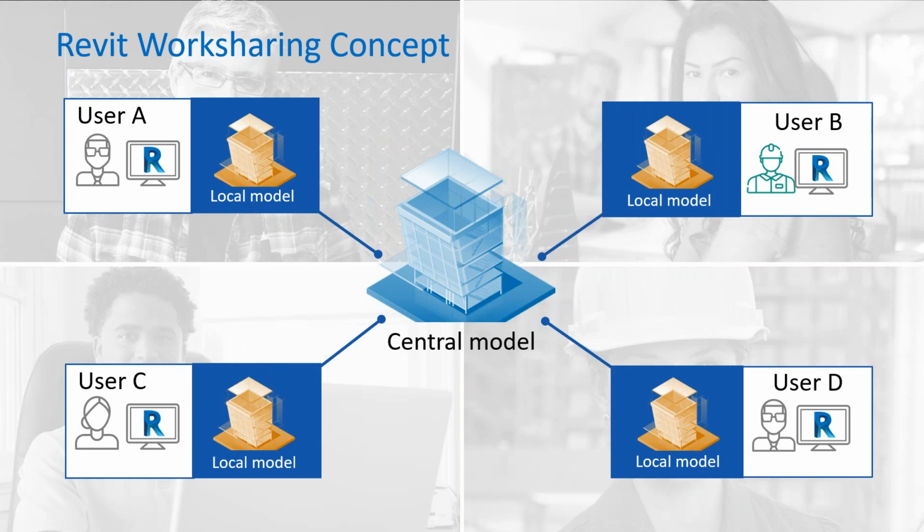And so what you see now is that BIM 360 design, from a timeline point of view, we started off within Revit, I guess 10 years ago or so, with central files on a shared drive, so an M drive or a P drive or whatever you have within the company. You'd create a central file, create local copies, and everyone would be communicating with this central model.